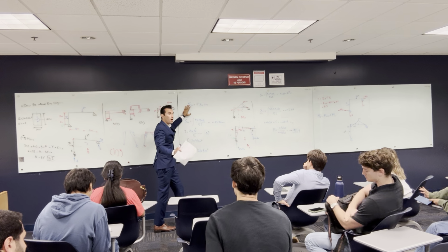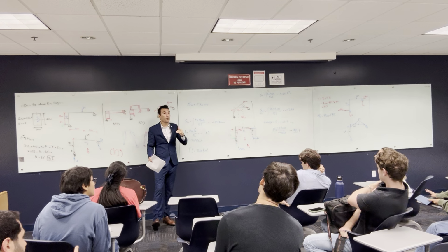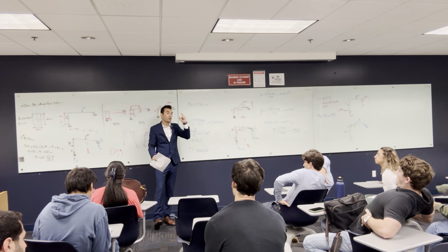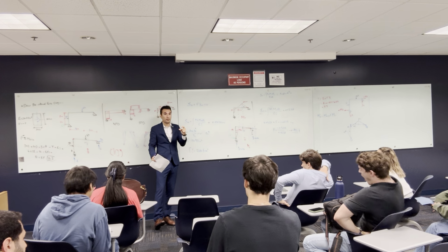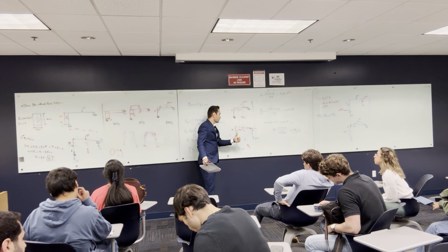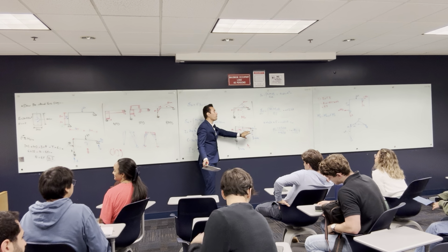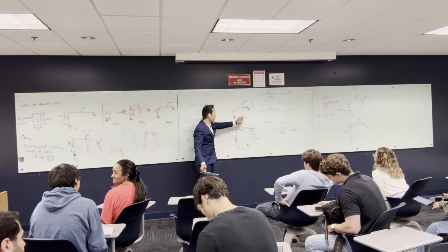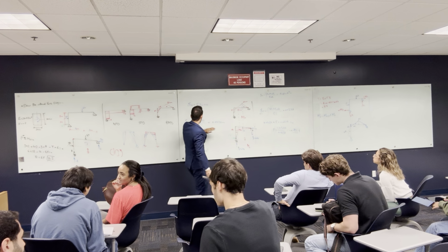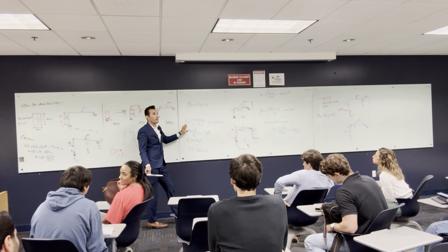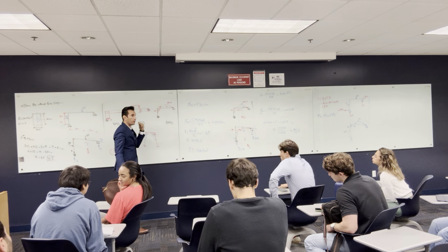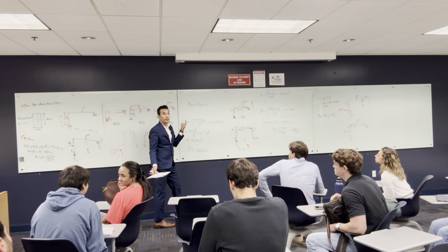That's for any problem. If you do this step by step, you are getting 5 points, 5 points, 5 points. If you mess up one, you're just going to lose points in the one that you messed up. So choose the main system right, get the bending moment right for this system, and then build the virtual system, get the bending moments for both, and then solve for delta 1,1 and delta 1,0. In the exam, I'm not going to give you more than one redundant. Only one equation. The one that has 3, I'm not going to give it to you. Just one.